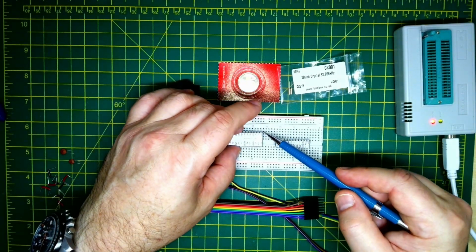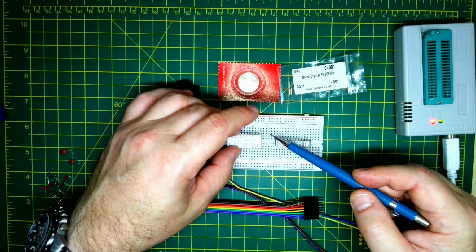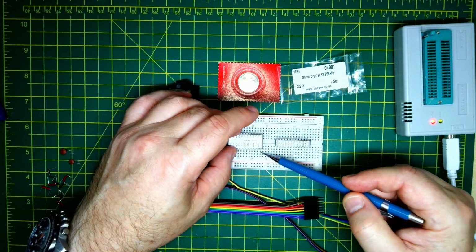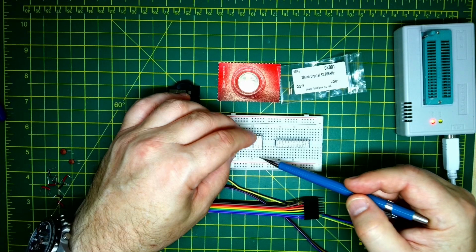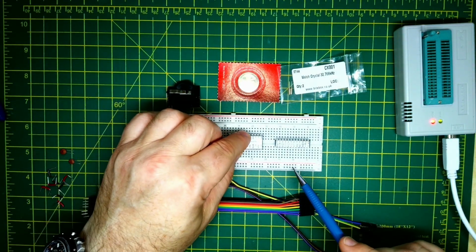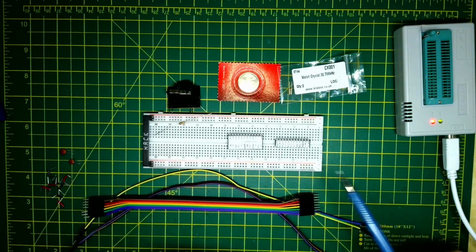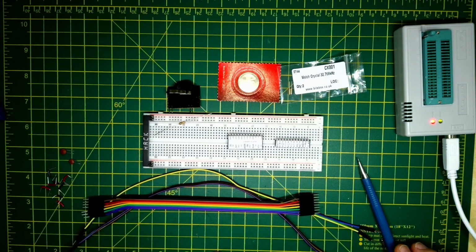Because this is a wider chip here, we need to decide whether we want the 2 holes on this side or on this side. I think we'll have the 2 holes on that side and 3 holes on this side, because there's a lot more stuff going backwards and forwards here. So that looks like it should be sufficient for us. So just going to plug those in. What I'm going to do now is speed this up and then I'll commentate over it. We'll come back once everything's ready to connect to the main board.